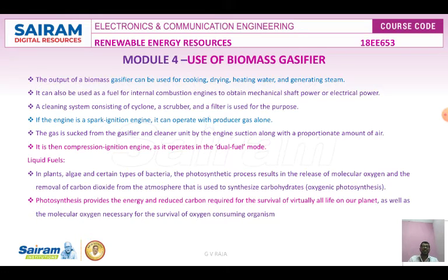So combustion is initiated with the diesel droplets and then spreads to the mixture of the gaseous fuel and air. So it is nothing but dual fuel. We are using biomass as well as diesel, that is producer gas as well as diesel, for this operation. This is nothing but dual fuel operation for the compression ignition system. And liquid fuels are also used when compared to gaseous fuels. The producer gas is also used for this internal combustion engine process.